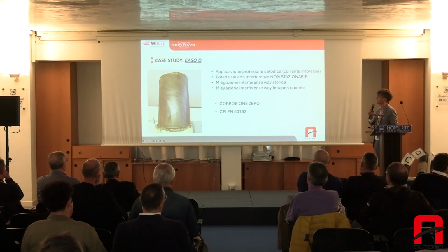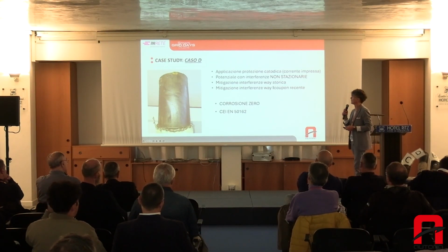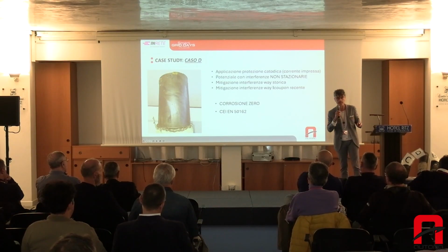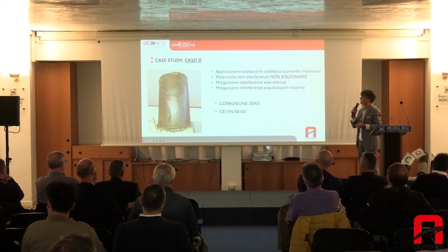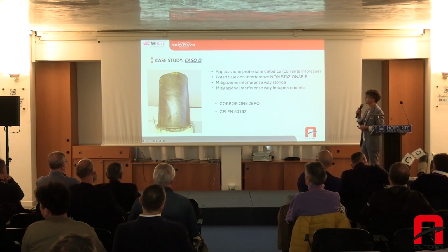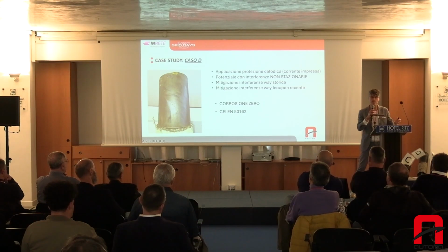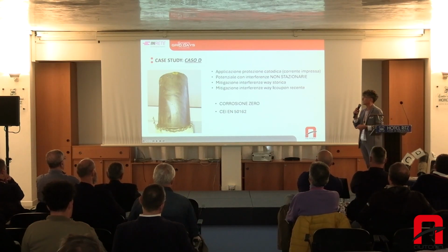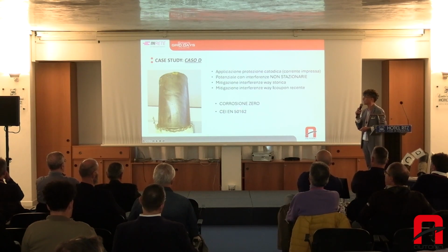That is not compliant. And apart from applying cathodic protection with impressed current, some non-stationary interference occurred, not right away, but some time later. So we did some mitigation activities.